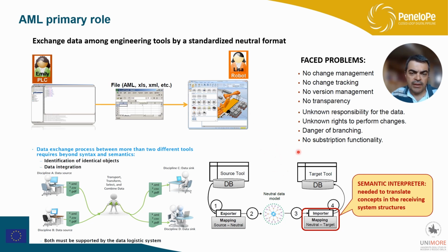And why have I recalled this basic path of information? Because when we export information and we use AutomationML, the concept of the file itself foresees that in the file we put the data, for instance the list of signals, but we need also to provide the semantics of the signals. So we have a definition, hopefully through a role class of the signal concept, its specification, for instance the data type, the range of valid values, and so on. So we have a description of the data along with the value of the data itself.